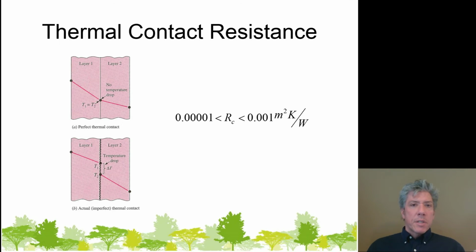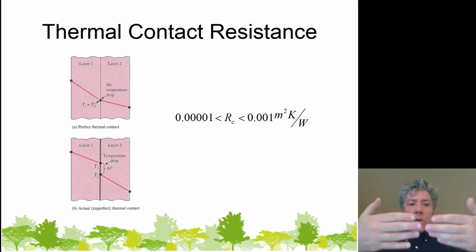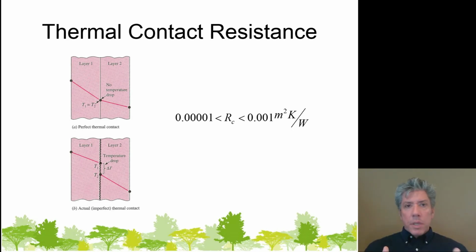Finally, I came to the realization that this was a TV that was backlit by light-emitting diodes. These light-emitting diodes are the actual source of the light, and then there's a screen that's a liquid crystal display, and it blocks the light when necessary. What had happened is there's several strips of LEDs on the back of the TV, and one of those strips had one LED that was bad.